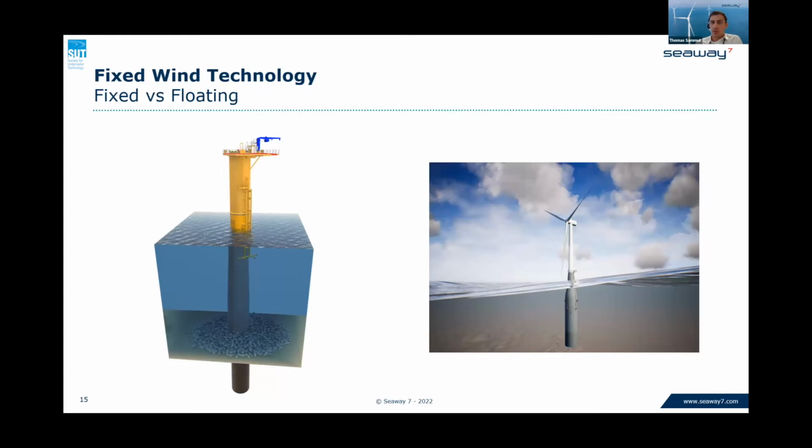The largest being looked at right now, the XL and the XXL monopile, is that 11-meter diameter. And there are challenges with going higher than that. Practical ones such as logistics, installing it, and also the issues related to the design, so the buckling effects and the bending.